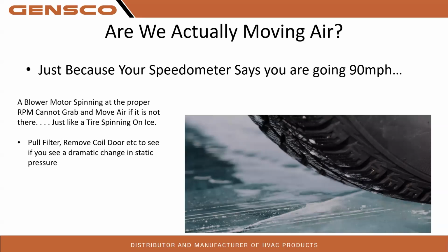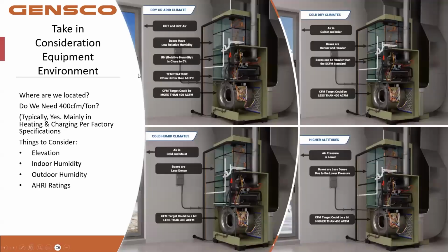Just like a car spinning its tires on the ice, and that blower is moving the RPMs, are we actually moving the airflow? We need to see that. We need to understand, are we actually moving the air? So don't get caught in the weeds. We need to look at our equipment.